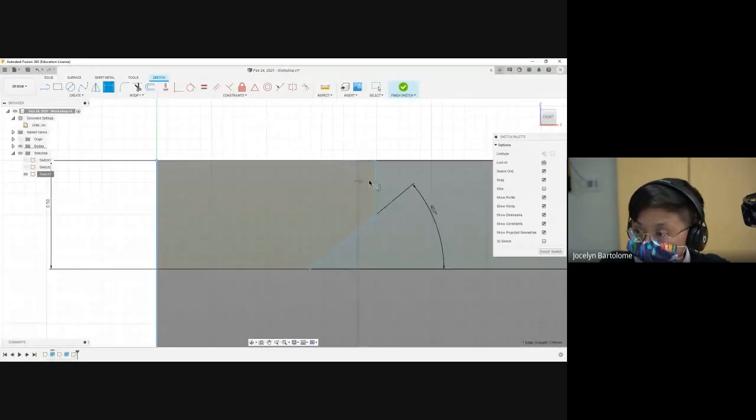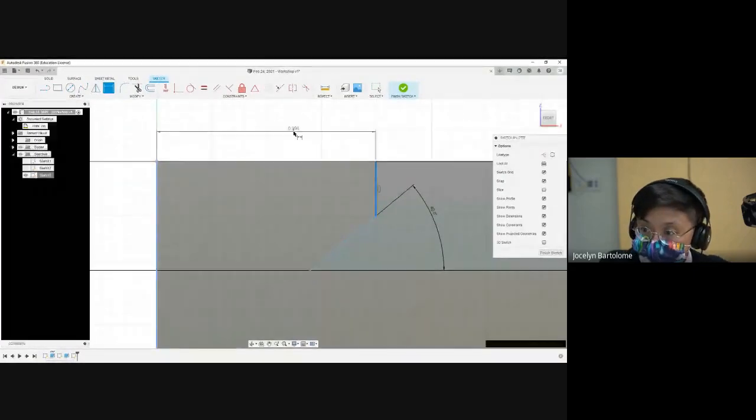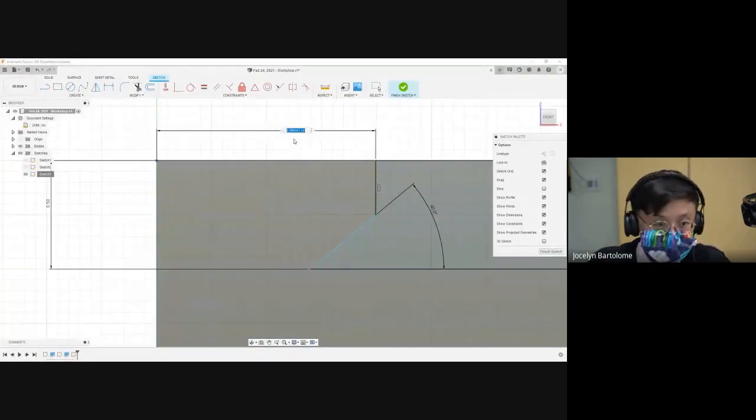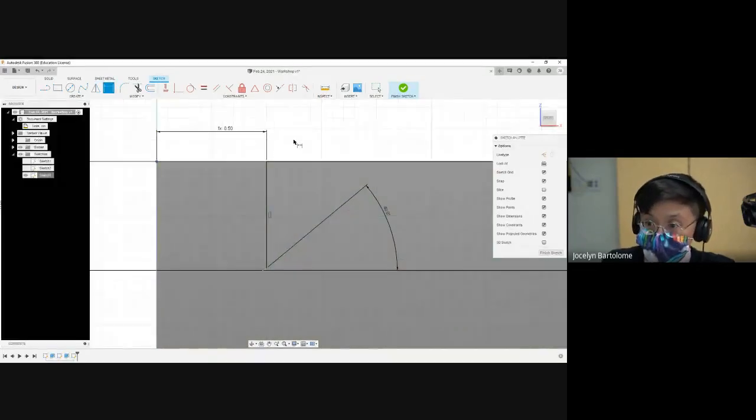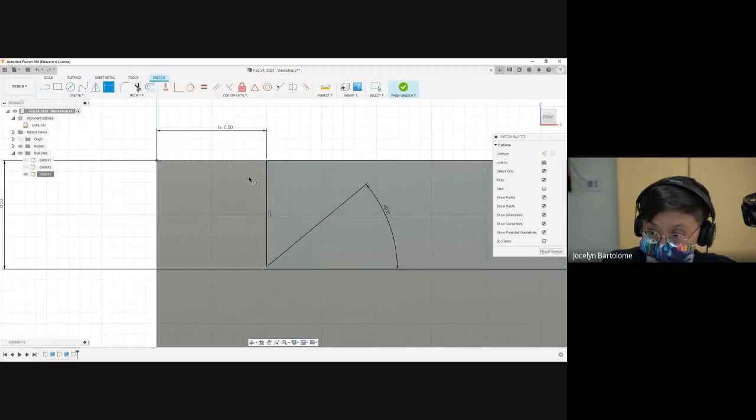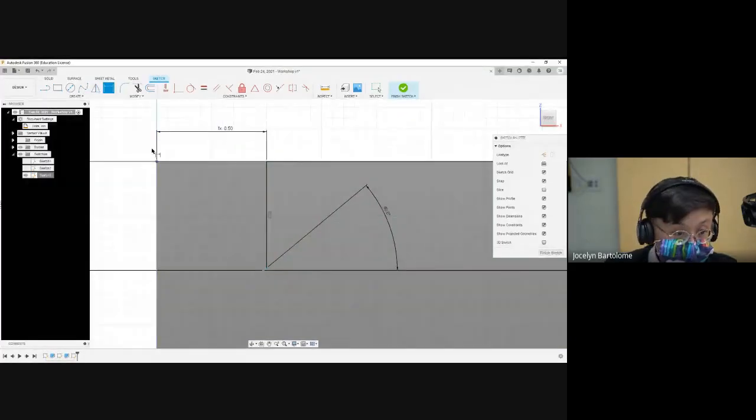All right, so click those two. Click once more. And instead of putting 0.5, you can just enter the letter number combination from before. So if you click OK, it will move everything over and show 0.5 centimeters.